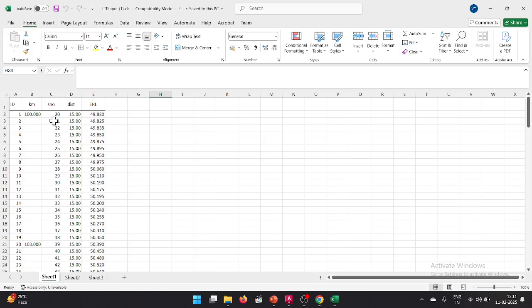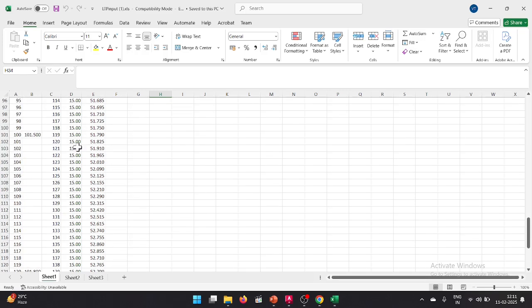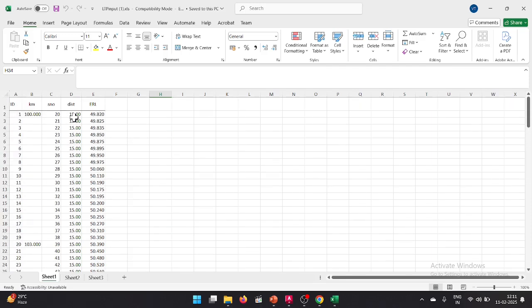It's only station number. You can put 1, 2, 3 like that, and between stations, what is the station interval. So every 15 meters you are taking the levels of the center of the track or road, so that it will give you the longitudinal profile. The existing profile will give. So 10 meter, 15 meter, 25 meter, 20 meter, you can make it according to your choice. A closer interval will give you a more perfect result.